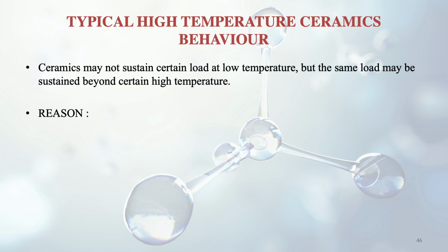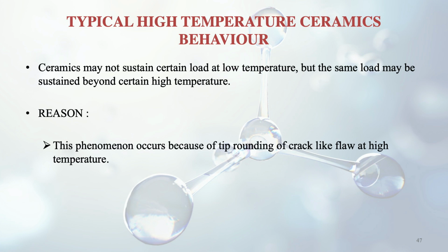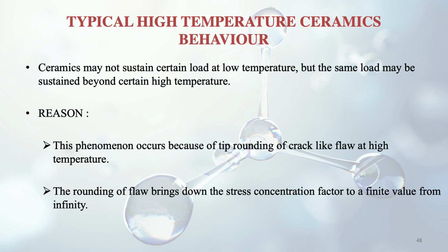Why? This phenomenon occurs because of the tip rounding of crack-like flaws at high temperature. If you take a specimen, there may be a small crack, and it may be expanding at high temperature. What will happen is that this rounding of the flaw happens.